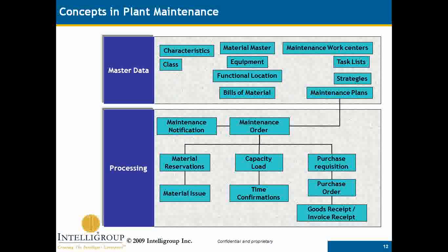any activities done, I have to write in the maintenance order. I have to perform all these activities: half an hour for this activity, half an hour for this one, half an hour for this one, and one hour for this activity. Every time I have to write it. So the repetitive work which you are going to do on the object, you can define as a task list. You can assign this task list to that particular technical object whenever you are generating the maintenance work orders.